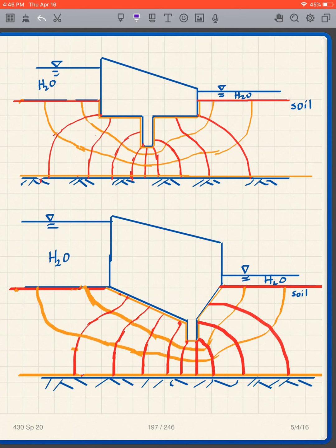So, in other words, for this particular geometry, there's my dam, and I have to make my flow net conform to the shape of the dam a little bit. Here's another one. Now I have a different shape of dam, just to make things a little bit different. And again, I have a high water table and a low water table, so once I know that, the water is going to be flowing in this direction, like that.